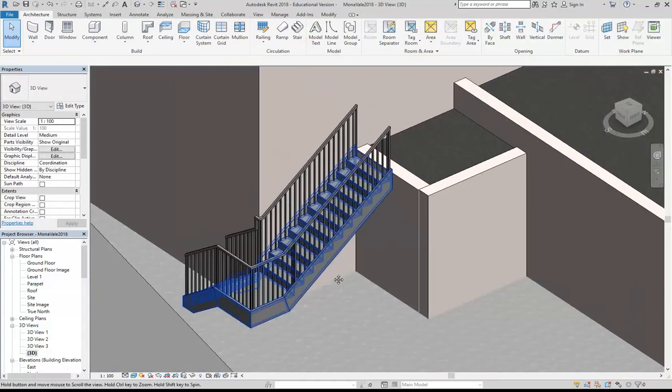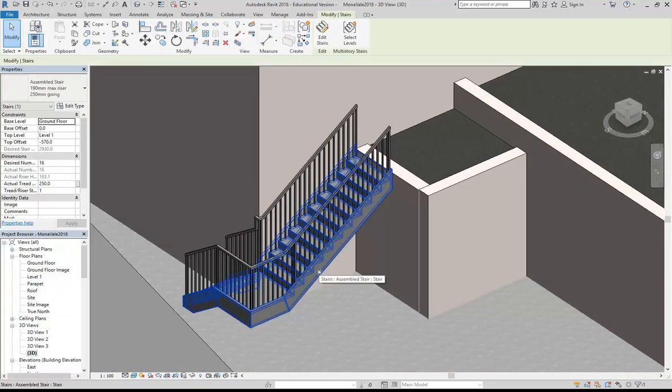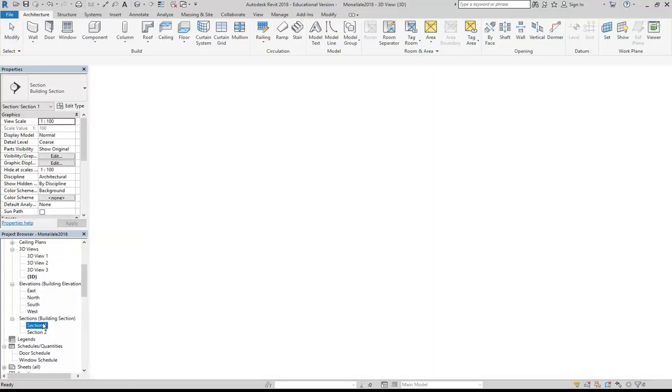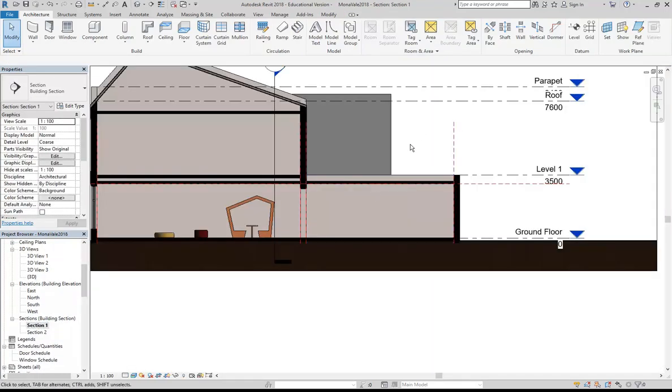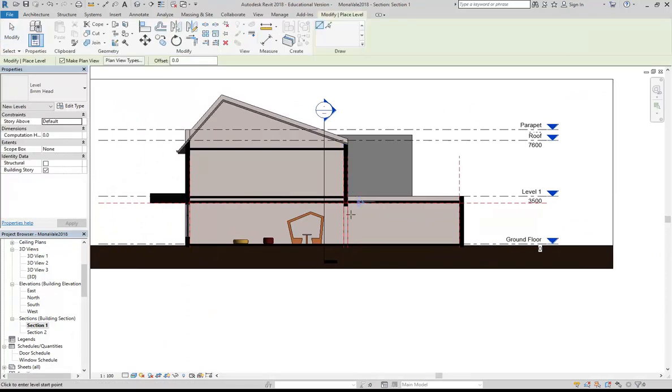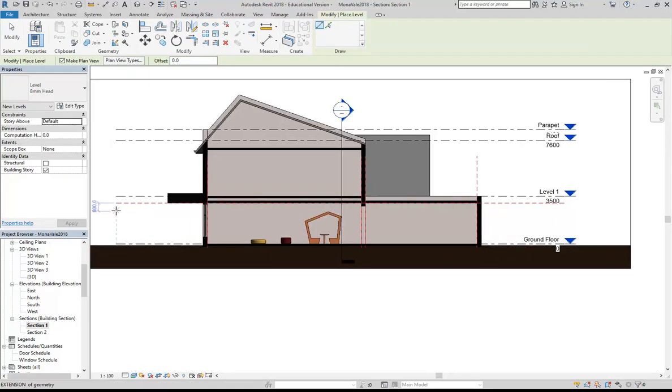But we can even do the calculations and work it out properly. So with the offset there, that's minus 570 from level 1. So to avoid having to remember that all the time, I'm going to go now and make a new level. This is what you'll often find when you're making lots of stairs. Make levels for them, and it makes your life easier.